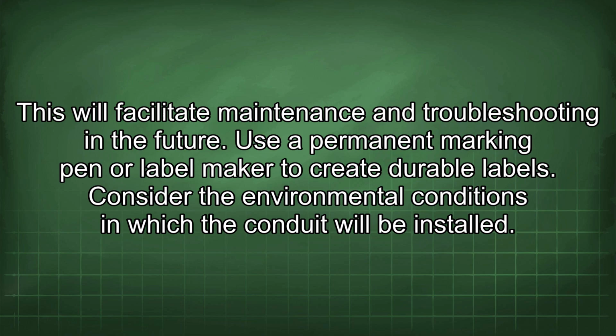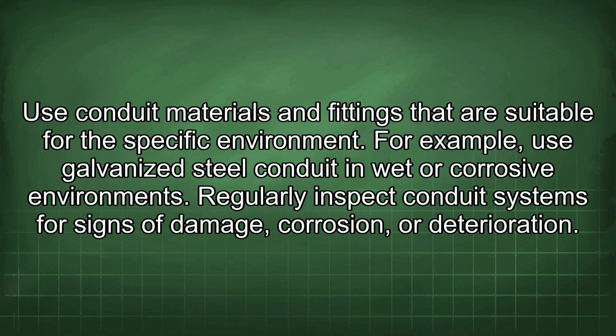Consider the environmental conditions in which the conduit will be installed. Use conduit materials and fittings that are suitable for the specific environment. For example, use galvanized steel conduit in wet or corrosive environments.